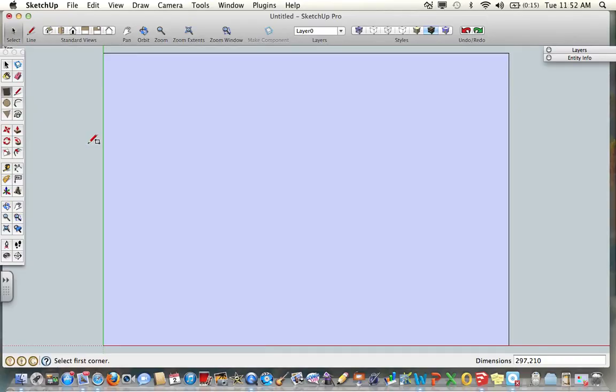The first thing we're going to do is add some guidelines. And these guidelines will help us make a border. So we simply take the guideline tool, click on the edge, hit the Tab key, enter 10, and then enter key. Bottom down the same down the bottom here, Tab 10, enter.